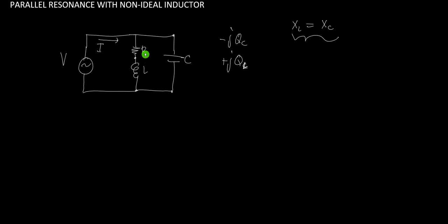So if you have a resistance here, this condition is not valid for this case because the sum will not become zero. They will not become zero because they don't have the same voltage across the inductor and the capacitor. If they have the same, then it's fine, it will always be equal to zero. And what should we do? How do we determine now the condition for this circuit to be purely resistive, so that it will be in the resonance phenomenon?